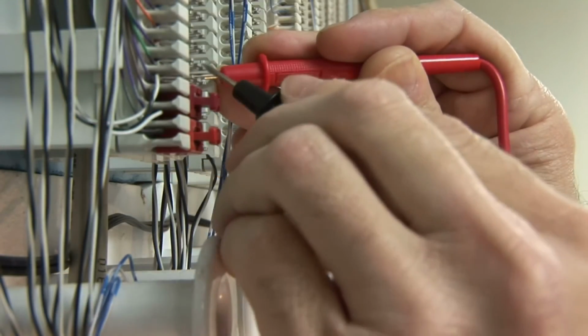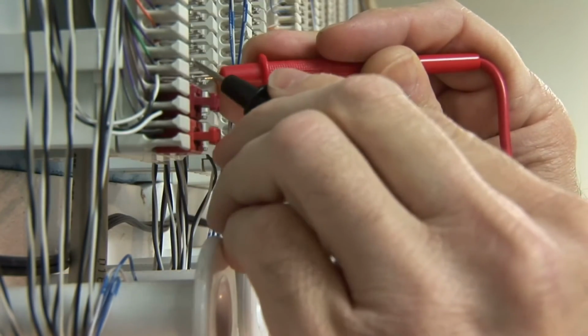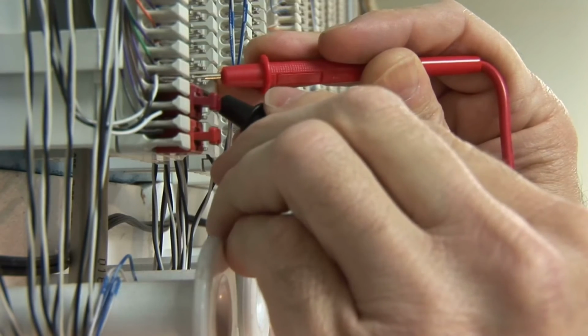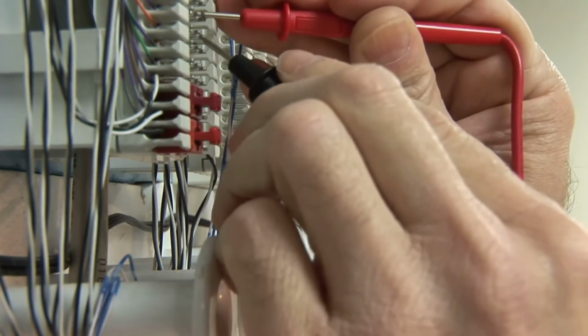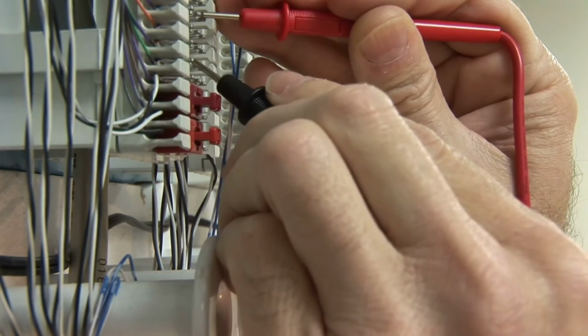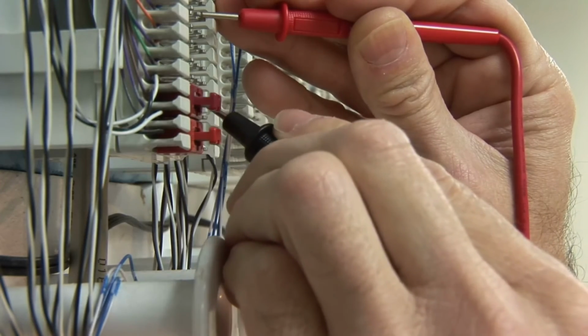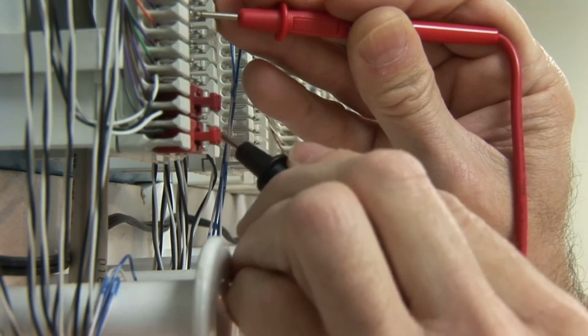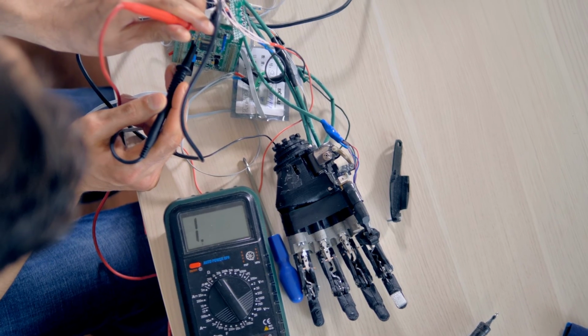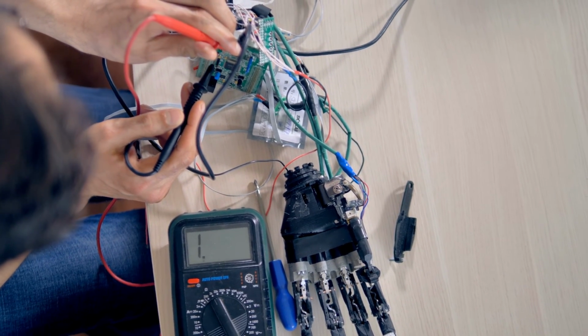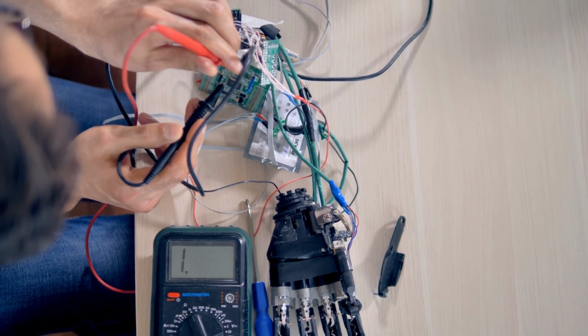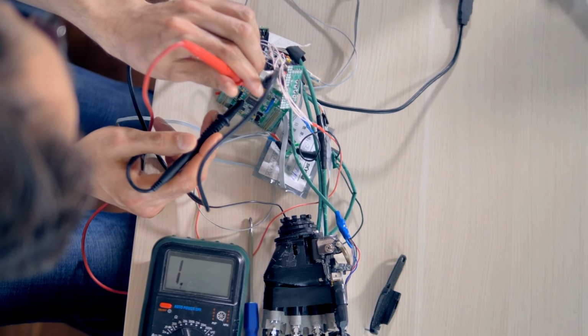The internal fuse of the multimeter was blown as a consequence, and repairing it proved to be inconvenient. It is therefore strongly advised that the dial on a multimeter be checked carefully before any connection is made. Ensuring that the correct mode, volts or amps, is selected can prevent potential damage to the device.